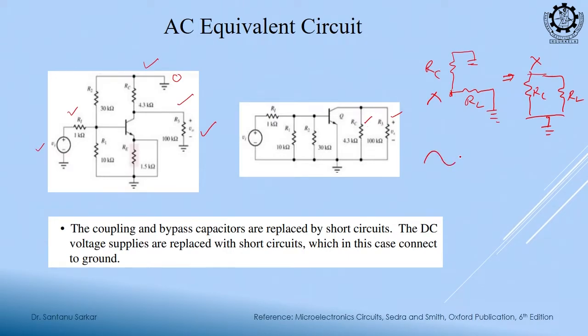this is our total current. I have a DC component, I have an AC component. So, if we consider the total circuit, then this is not true, but for only the AC component this DC part is equivalent to 0. So, now the circuit is redrawn, and in that case RC and R0 come in parallel.